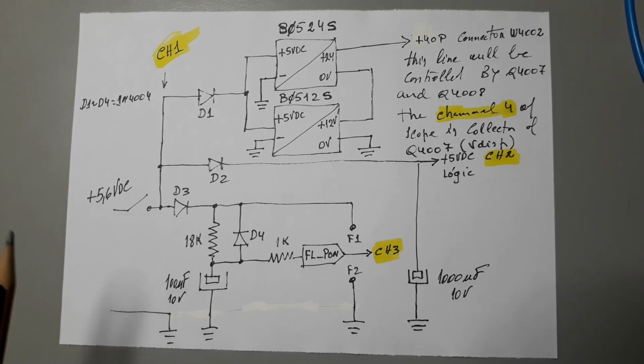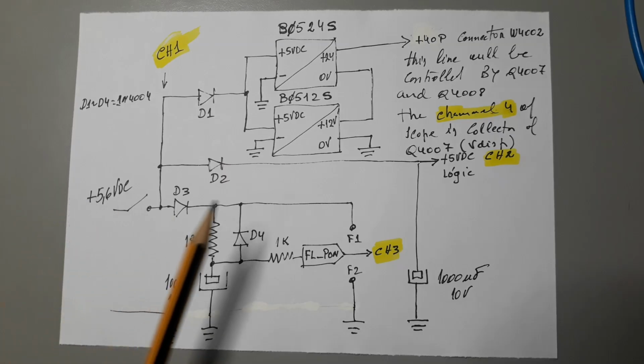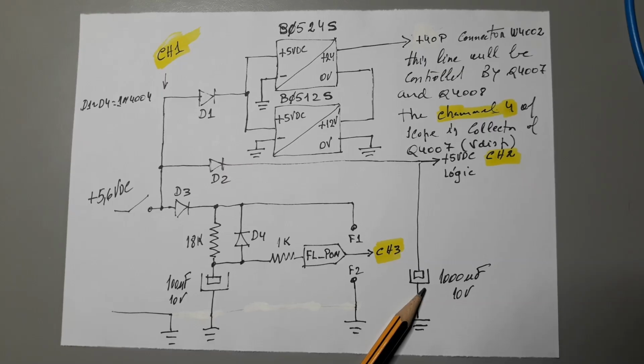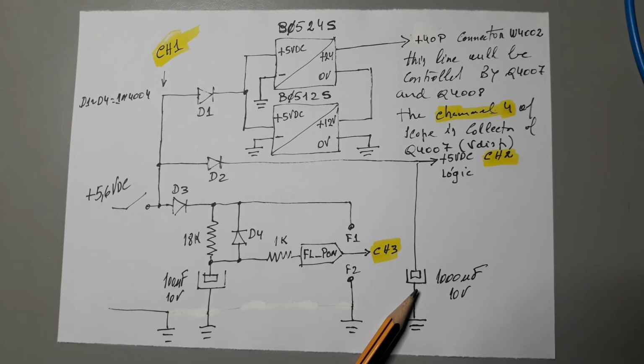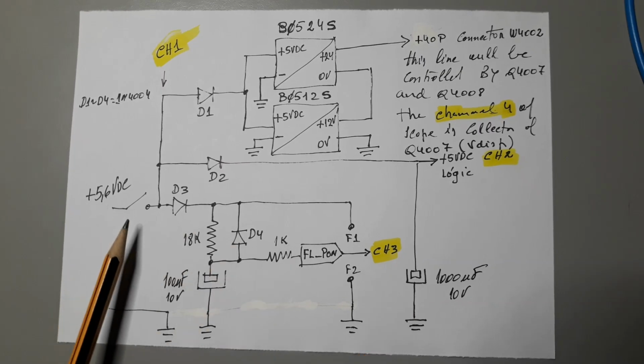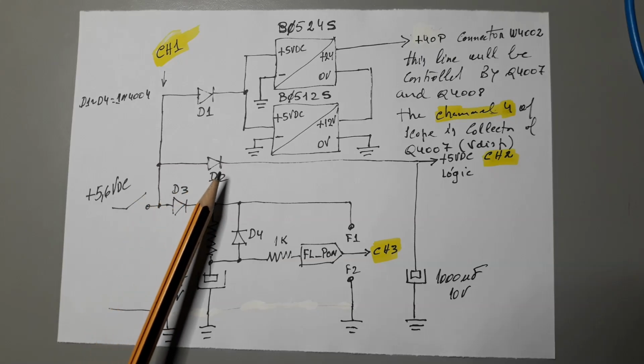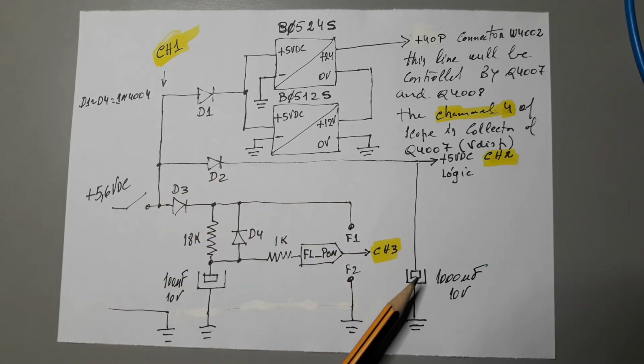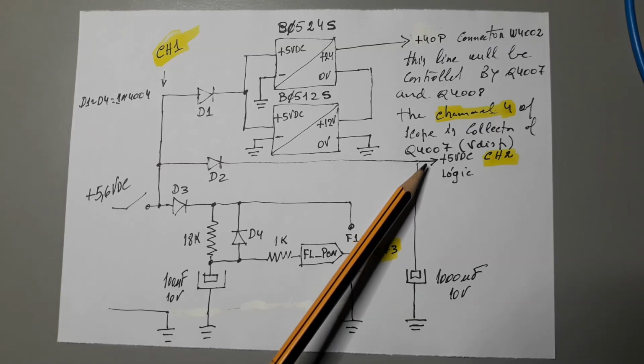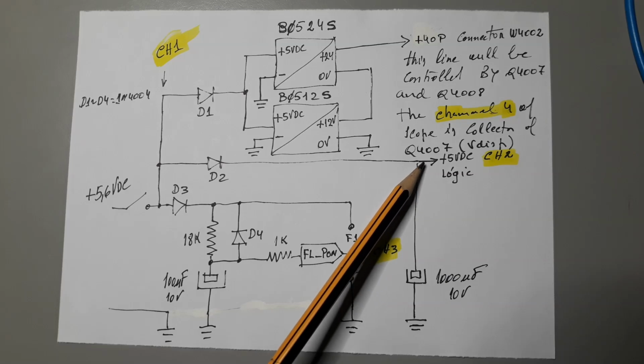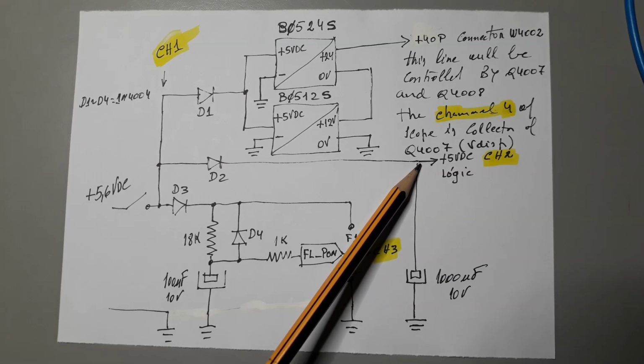The process to release the power is the same. When you disconnect the power, you have this capacitor here with a total load, okay? Because it's loaded by this diode here, and you have the plus 5 volts DC present here, because the wire to the plus 5 volts logic comes to this point.